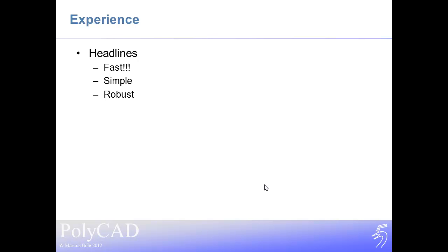Because it's so simple, it's incredibly robust. We no longer have to worry about the topology of the curves, where the curves are connected. We can practically give it rubbish. And because the curves, splines that are being intersected through these definition curves are only based on point proximity, it's very difficult to come up with a scenario that could cause the software to crash. And because of that, it's a very tolerant process. We can use this to kind of identify a hull form before we get to the stage of worrying too much about our surfaces.